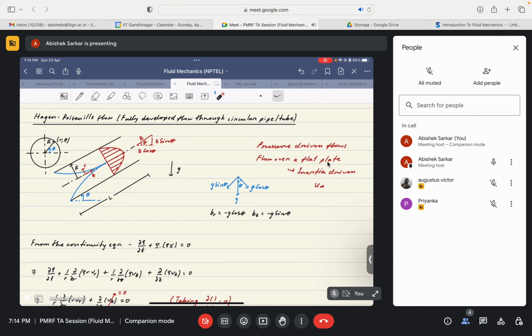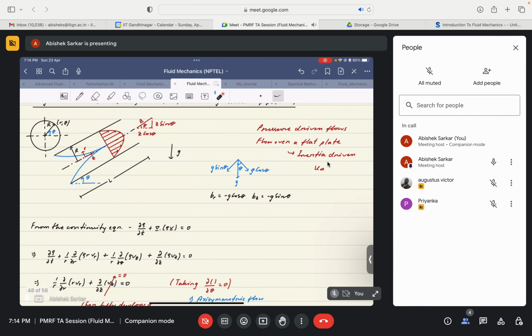Again, in this diagram, I would not like to discuss the diagram extensively. I guess it was extensively discussed in the session while discussing the Hagen-Poiseuille flow and the flow through pipes. So I don't think I would like to repeat it for both the cases, but still this region, where the flow is developing, or basically the velocity profile is developing, is known as the developing region, or the entry length, and the length up to which this developing region occurs is known as the entrance length.